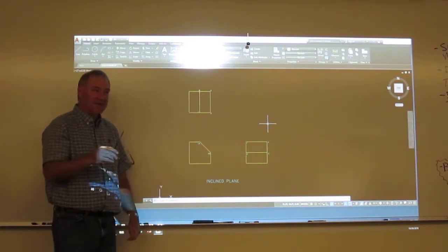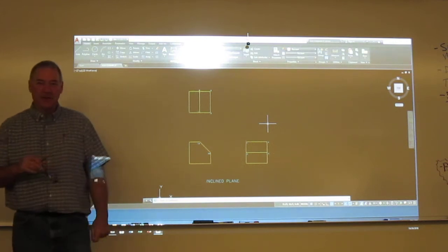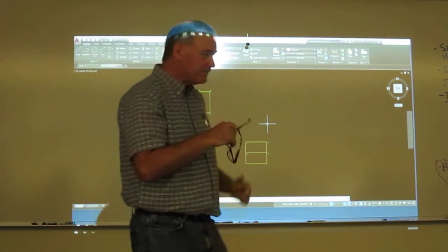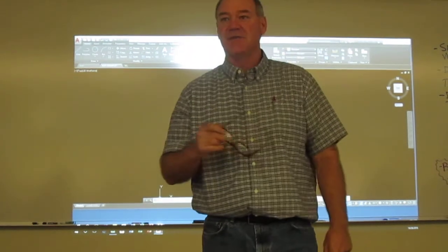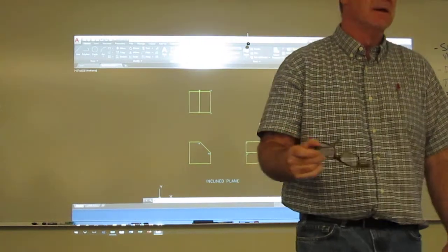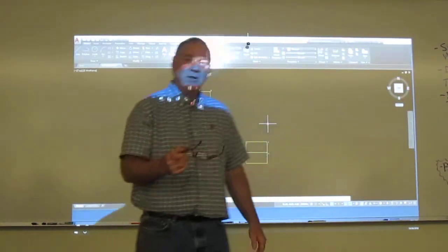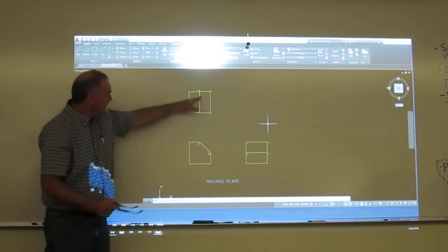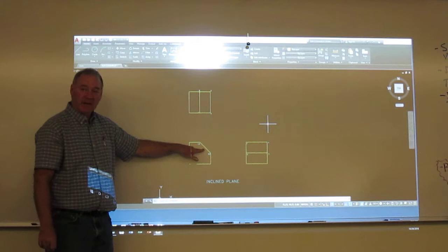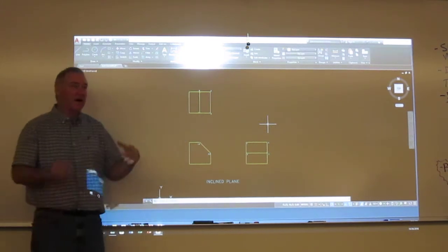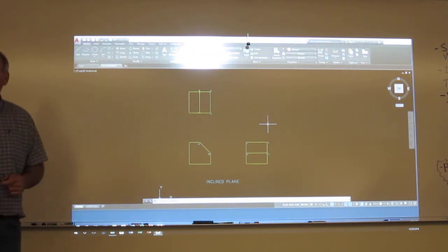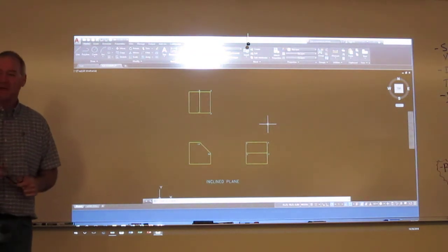So if you want to relate this back to the laws of descriptive geometry, you would look at law 3, which states that a plane appears true size and shape in the viewing plane parallel to its edge view. Okay. Now that's a law. With an inclined plane, don't we see foreshortened, and an edge? Yeah. Okay. So in essence, we've already got an edge. You're at law 3, because you've got an edge view. So therefore, we can find true size and shape with one rotation.